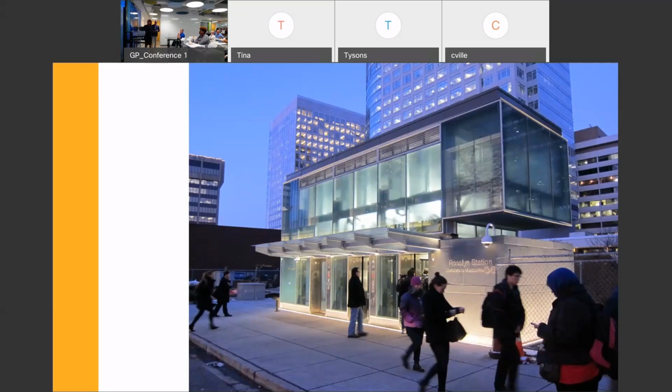So it's just sort of grazing the vertical surfaces here. You can see the signage, you can see the glass elements, and where we have the walkways, we changed it to just a glowing line of light instead of something with optics, so it doesn't blind you as you walk over it. That's the only element lighting the space, but you can clearly see everything. There's still safety, and there's still wayfinding throughout this whole area.